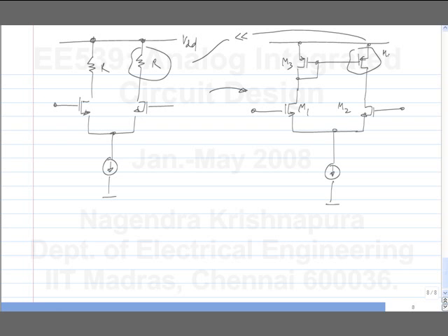So let's say we terminate this in an incremental short circuit. What is the output noise current because of M4? If this is the output current, what is the noise current because of M4? What is it? Yeah, it just directly comes out. So the noise spectral density because of M4 is 8/3 kT GM. What is the impedance contributed by M4?